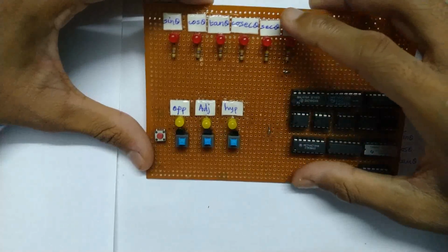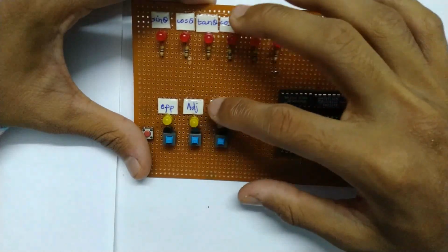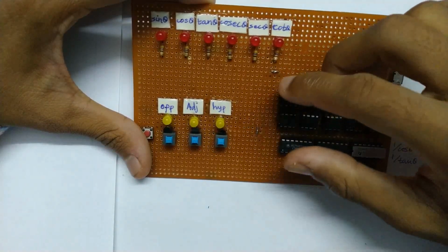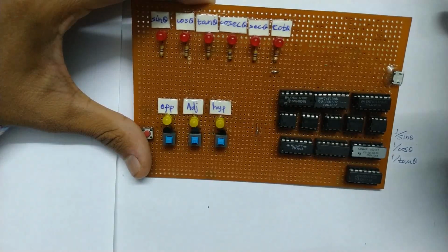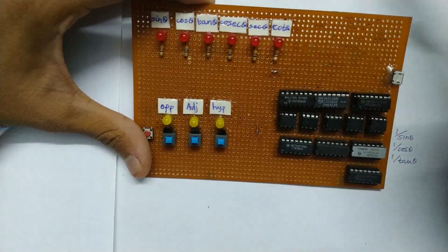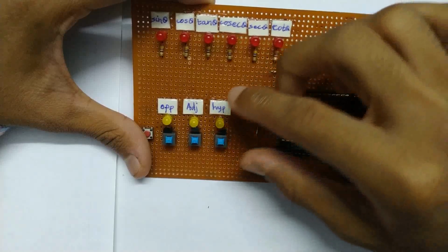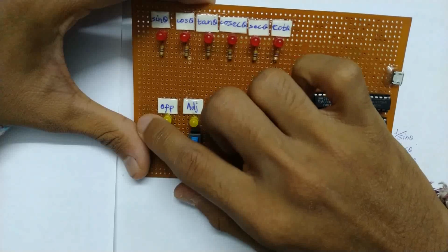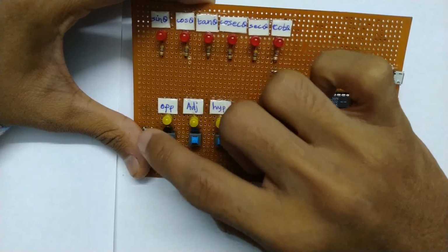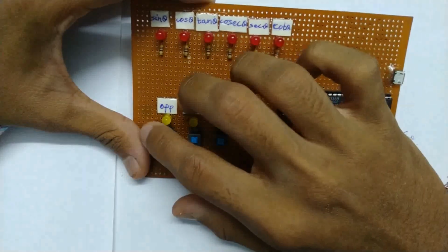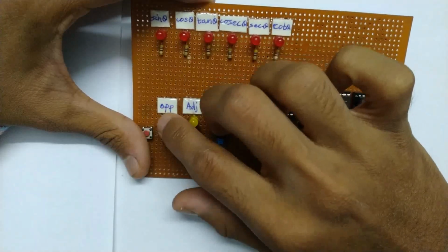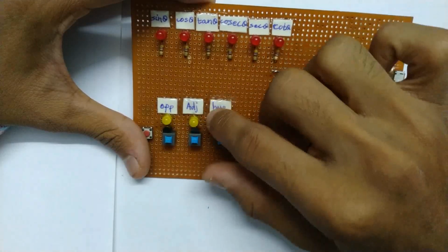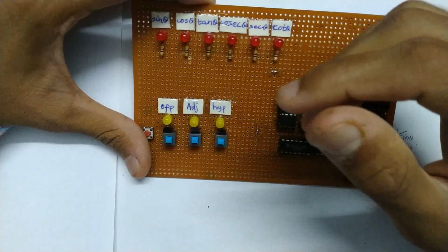So what I did was, obviously, use combinational logic. What combinational logic defines is that the output of the circuit depends only on the present input. What that means is, once I click hypotenuse and opposite, and then click this push button, it'll just take whatever it gets. After I push the button, it'll see that opposite and hypotenuse are on. In binary that is 101, which is five, and I'll just take this five and do whatever with it.